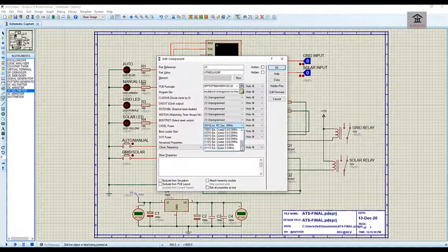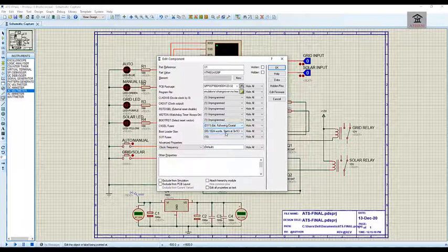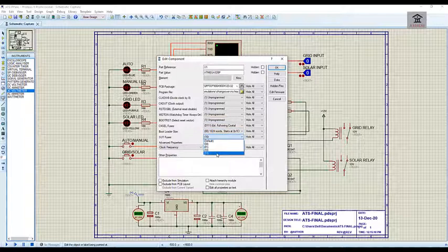So I'm going to choose external crystal, which is a full swing one, like this. And then do I want a bootloader? No. What are my startup fuses? That's how long should the microcontroller take to start on? I'll choose 1. You can refer to the data sheet of the microcontroller for more information on that.